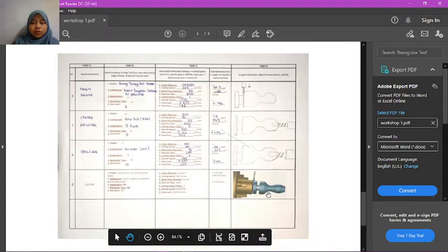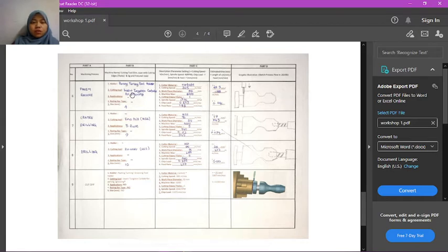So we go to the next step, which is the finish groove. For part B, we use a cutting turning tool holder for the holder, and we use the cutting tool which is an insert tungsten carbide for grooving, and there is no application and boring bar type, and the size is 4 mm.